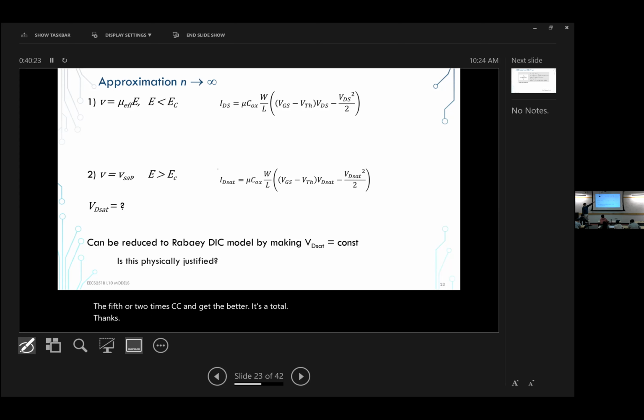So you essentially end up with 2 equations. One of them is the equation that corresponds to a standard device that we have seen before. And the other one is the velocity saturated device. How do you divide between the 2? When do you use one? When do you use the other one? It's kind of hard to figure out where it does. When do you switch between those 2? On the bottom of the curve, you're going to be quadratic, and then you're going to go to more of a constant level up for higher VGSs. And this delineation between the 2, VDSAT, is not that deep.